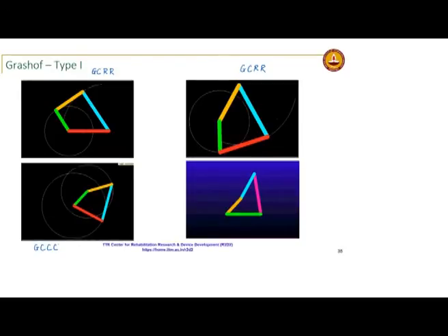And the fourth one is where the link opposite the shortest link is fixed. You will see that it is the coupler that is tumbling in the plane. It is not rotation about a fixed point, but it is undergoing a complete revolution. So, it is called a tumbling coupler. This is the link opposite the fixed link. So, you have the Grashof rocker crank rocker.